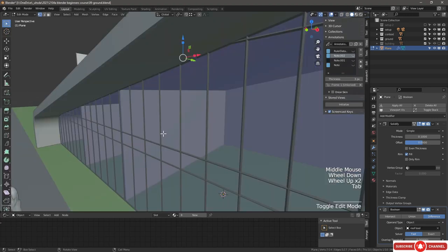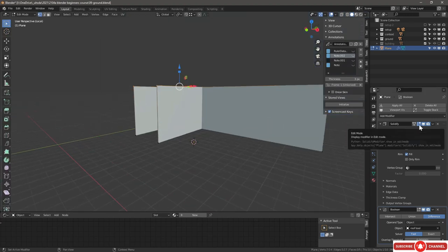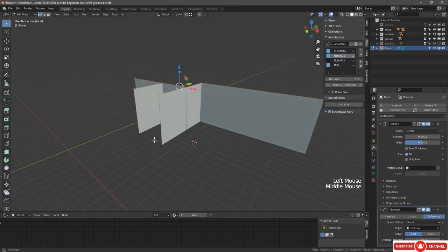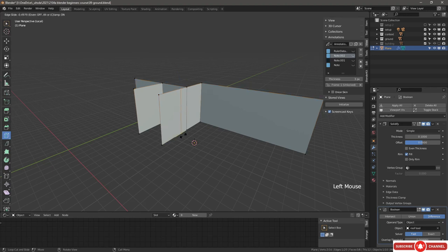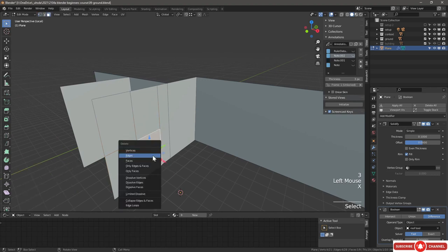two. In edit mode, I'm going to isolate the object, slash. Turn on the solidify modifier in edit mode so we see what we're doing a little bit better, and let's use our loop cut tool from the toolbar. We want a loop cut here, so click and hold, another one here, and then one over here. Next, let's get rid of this face, X, faces.